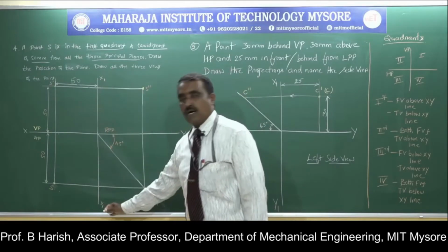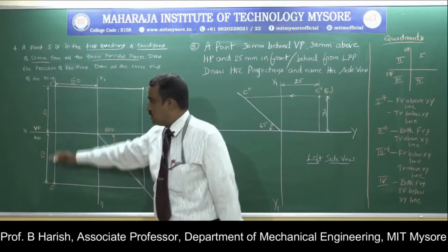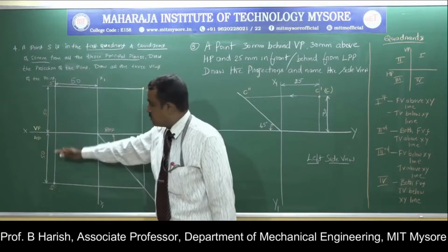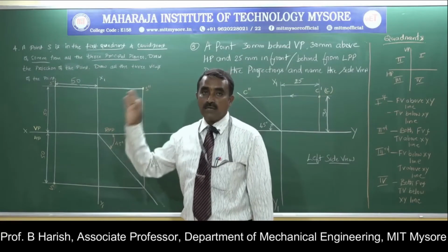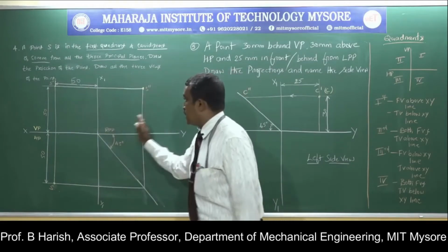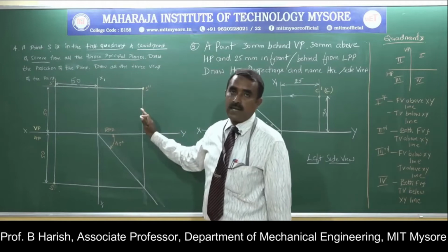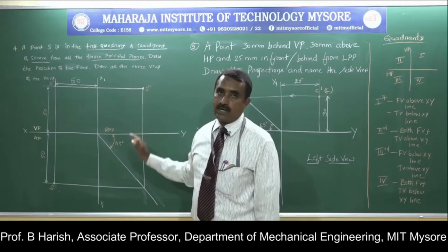Now I have already drawn the profile plane. Here is my front view, here is my top view. That is, in this plane I got the front view, in this plane I got the top view. So I should get the profile view. Always front view and profile view will be in line. Hence in this plane I should get the profile view. That is what I have to locate.